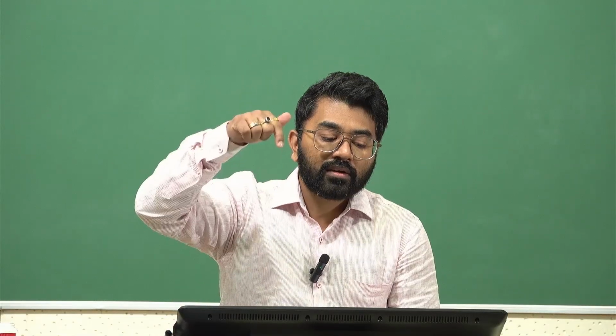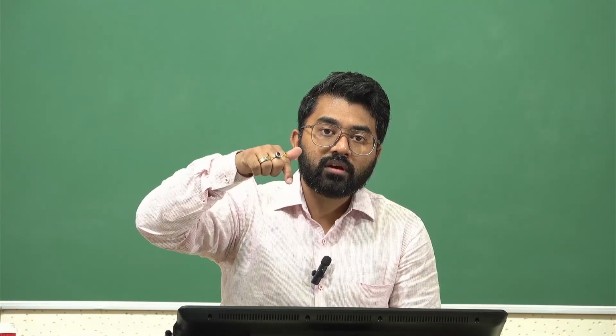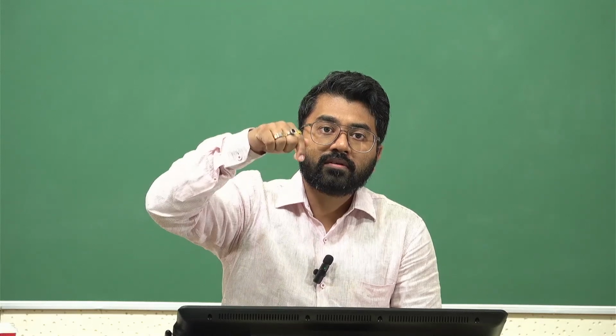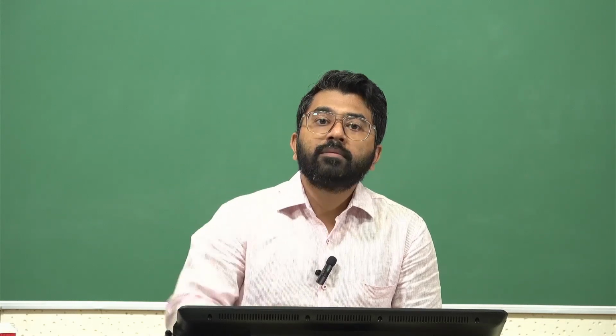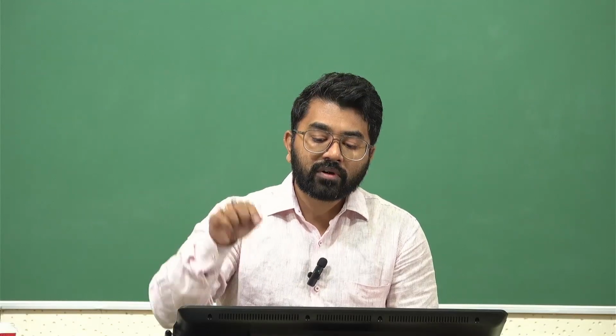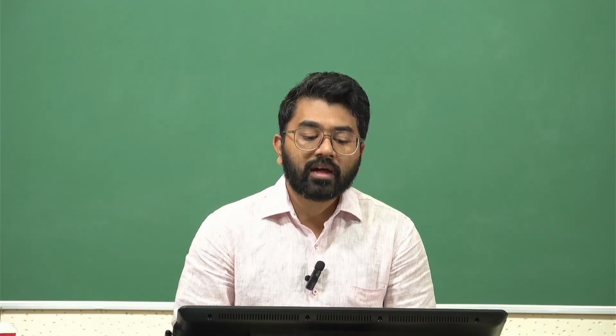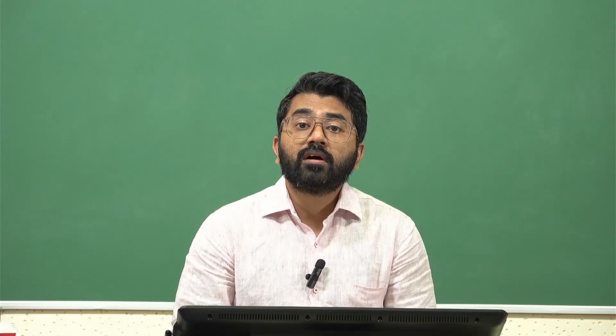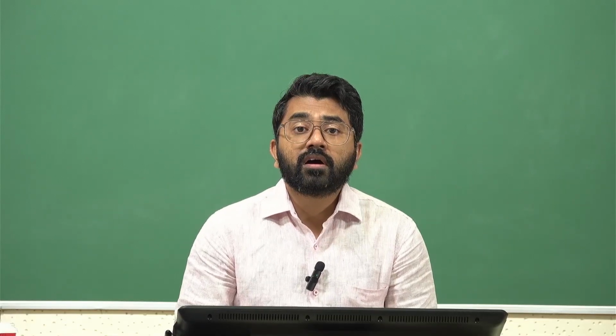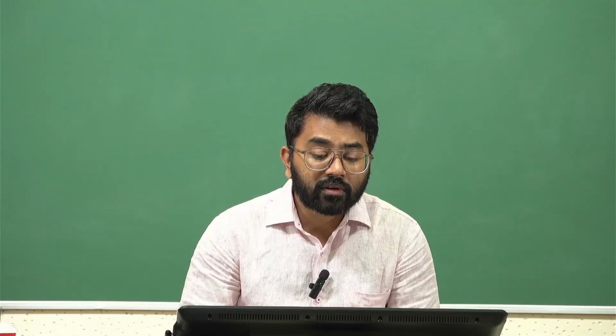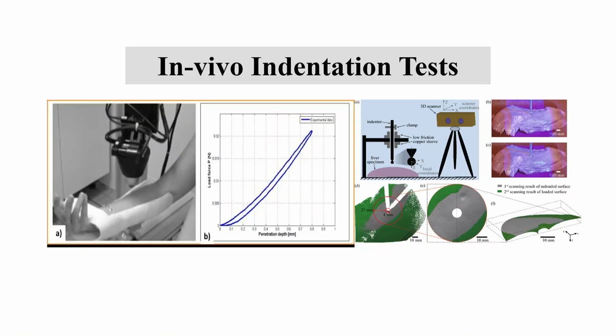And then you have the indenter, which comes close and takes a little bit of a dig, just kind of pokes onto it but doesn't really penetrate. So the indenter doesn't penetrate but just pushes onto the skin and tries to take a dynamic measurement. So the measurement is something which you look at in the plot here. You're reading load force in newtons along the y-axis, and you're looking at the penetration depth in millimeters along the x-axis. So you could well imagine this penetration depth is 0 to 1 millimeters.